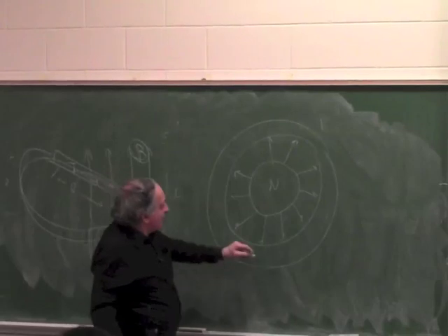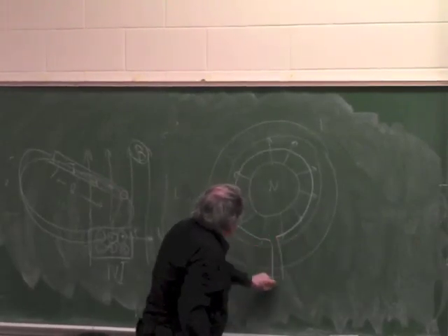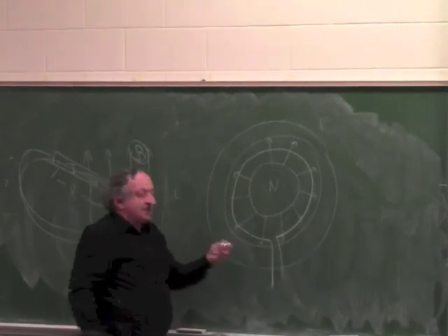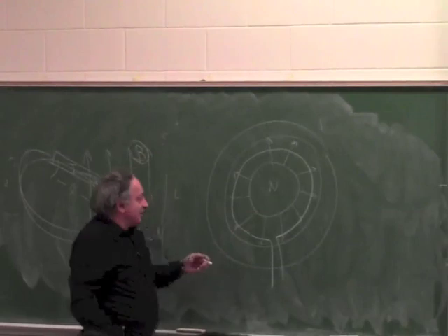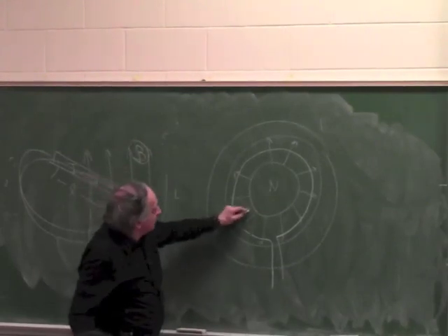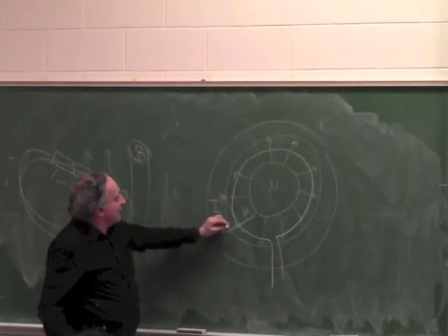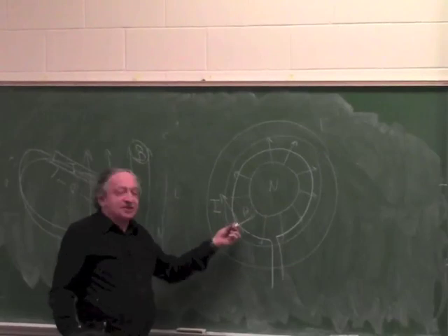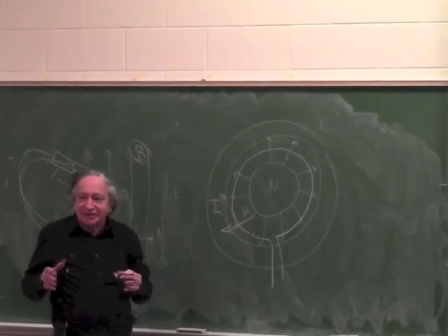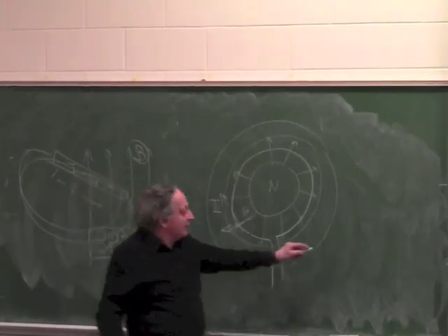Now if I put a loop of wire in the radial field, every bit of wire will have a force on it pushing in this direction. Because remember the three vectors are perpendicular, so I have B in this direction, I have I in this direction, so BLI will come out like this, or like this, depending on the direction of the current. So if I make the field radial, every piece of copper creates force, and then I get 4 out of 4.